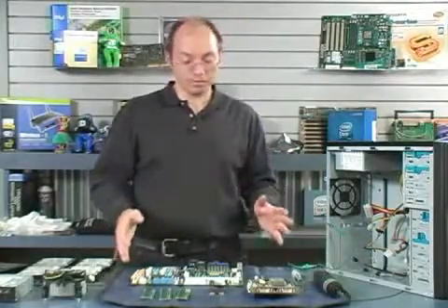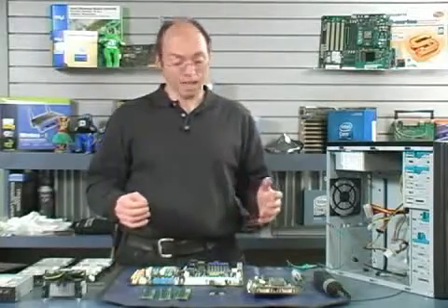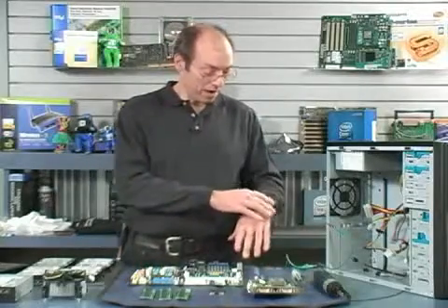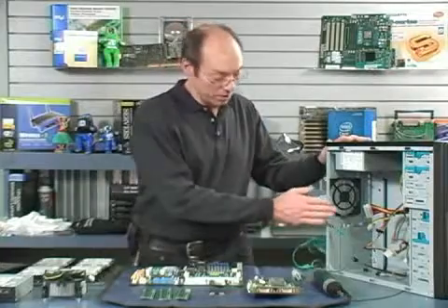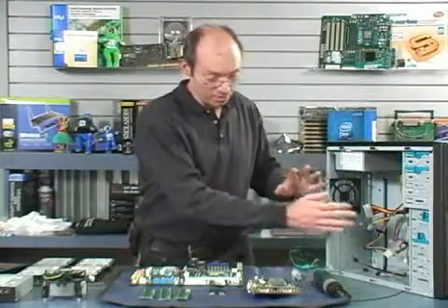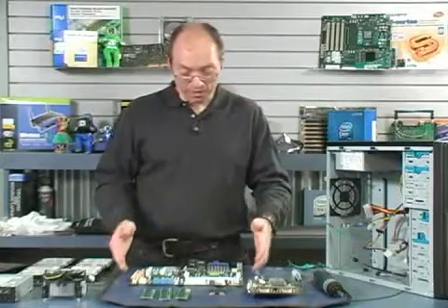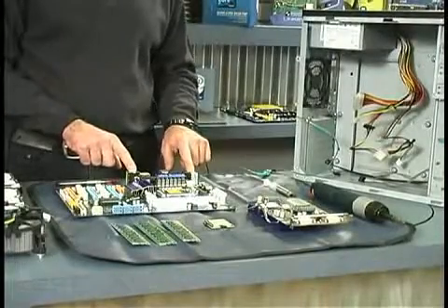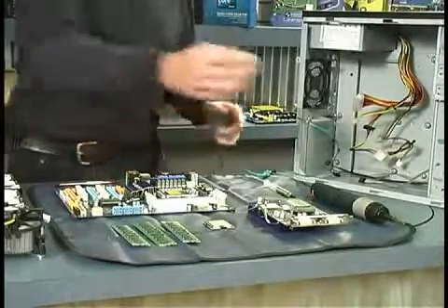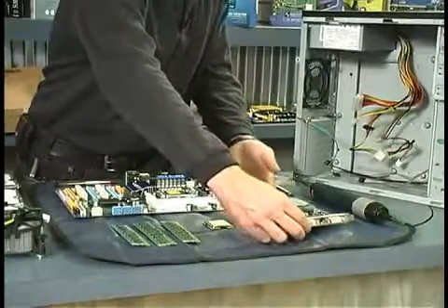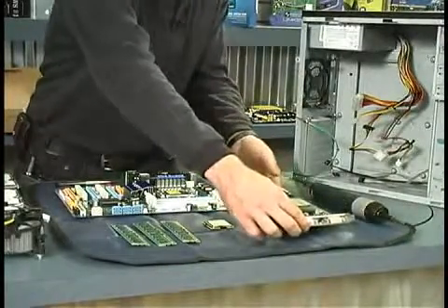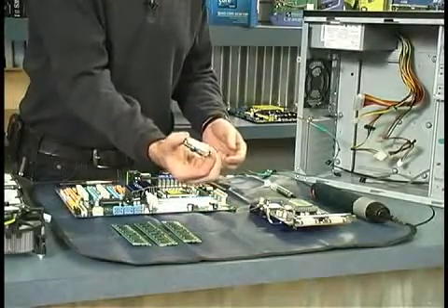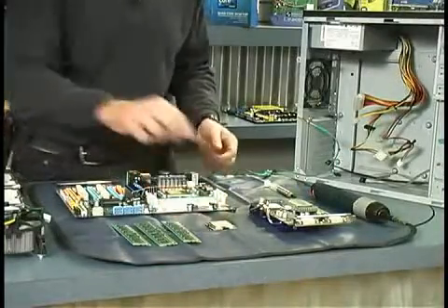These parts are expensive, and you don't want to risk damaging any of them due to a static discharge. Now, if you don't have the wrist strap and such, what you need to do is touch the frame of the case every time you go in to handle something. And if you're going to grab the motherboard or a circuit board that's out of the PC, touch one of the grounded metal areas, like on the connector shells, or in the case of a card, touch the metal bracket before you pick up the card. And it's best not to touch any of the components. Processors will come with a protective covering over the pins or leads, and you want to keep that on until you are ready to install it.